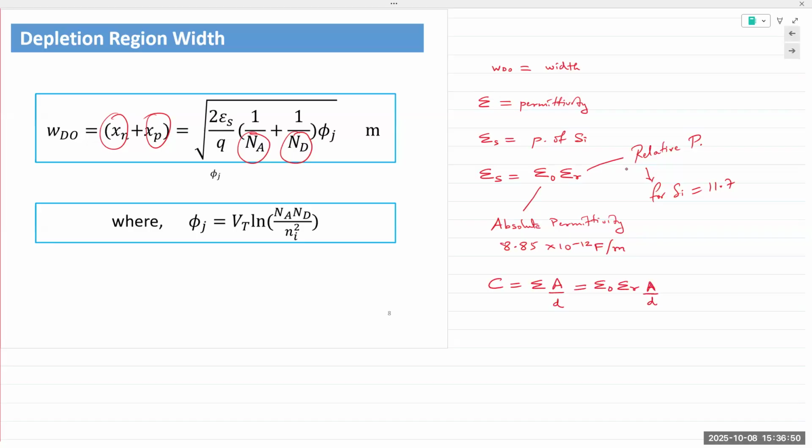Okay. So permittivity, basically how much charge can we occupy? There's a point to this. Because we have charges that are stored on either side of the junction, this can be modeled as a capacitor. So every single diode has a junction capacitance known as CJ, CJ0. There are special diodes that are used as voltage control capacitors known as varactor diodes.